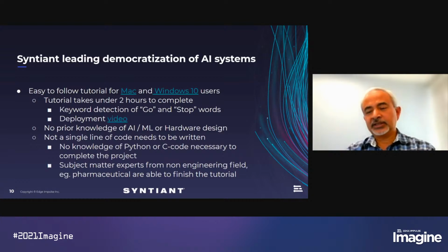So yes, this board also has a similar architecture. There is a host processor and that has an M0, Cortex-M0. But during the normal mode, like during the inference mode, that is shut down, that is in sleep mode, because some of these host processors may be taking a lot of power and we wanted to save that power. So that M0 isn't really expected to do anything during the inferencing mode, while the NDP101 is on and doing the heavy lifting.